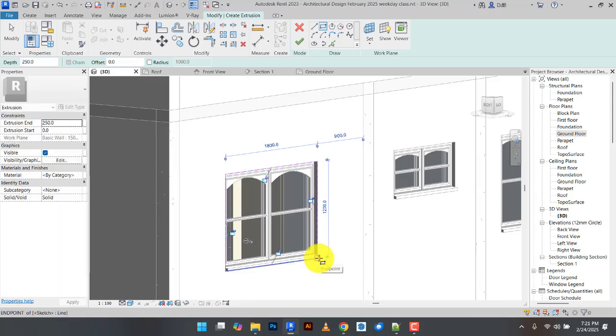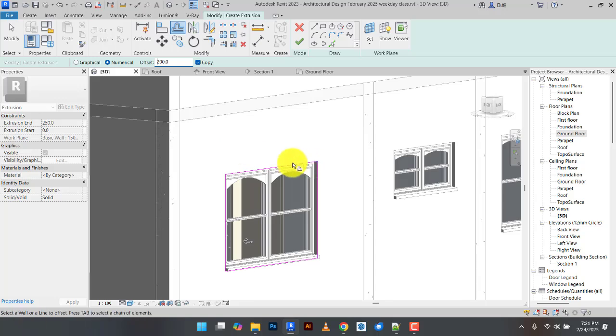If you accept this, it means the extrusion will cover the window. But I want it around. So you have to draw another one around so that the inside will be a void. The same analogy. I'll use offset, and I'll offset it with the value I intend. If I do 200, it's too big. What should I do? 75. All right. Then copy: I'll click copy, click it again so that the cursor is out of that side, Tab, click. That's all. Then you click on accept.